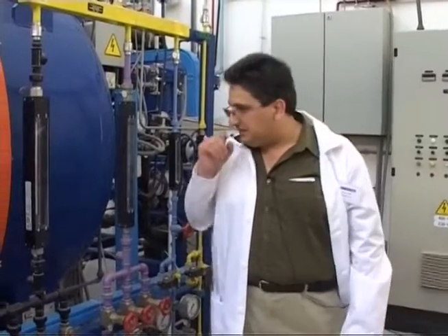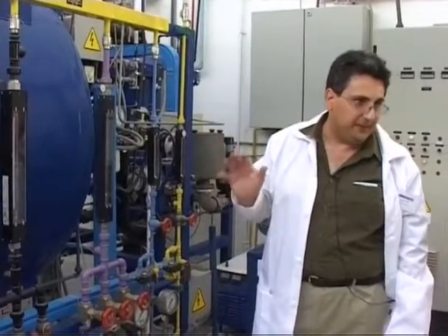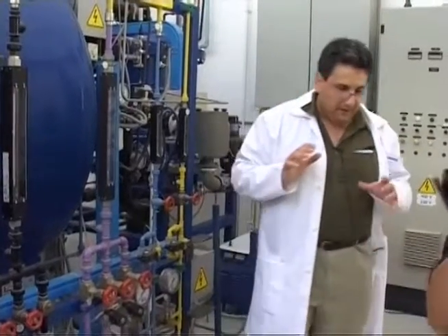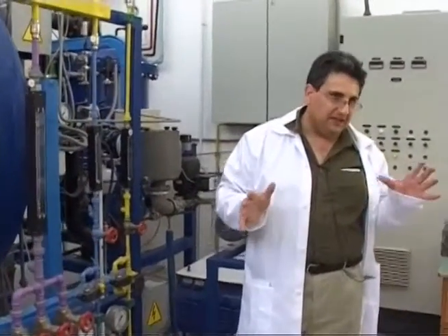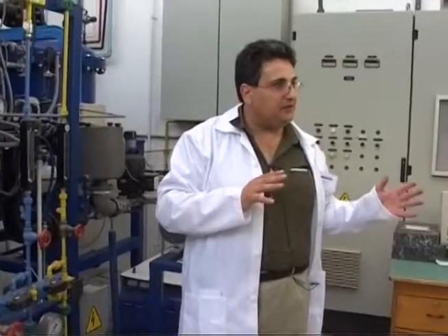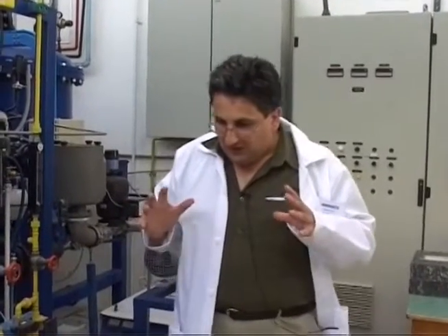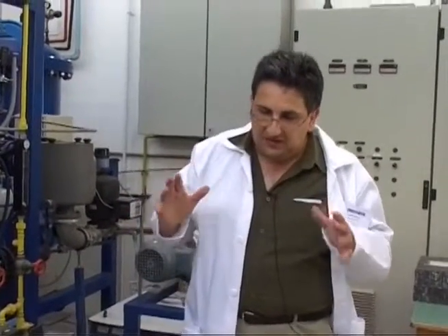The next step is heating the components to the required temperature. Now, nitriding is usually conducted in the temperature range between 450 to 570 degrees C. Heating components in this range, which is considered to be low temperature in surface engineering terminology, is a very slow process in vacuum because the energy conducted by radiation at those low temperatures is very limited.